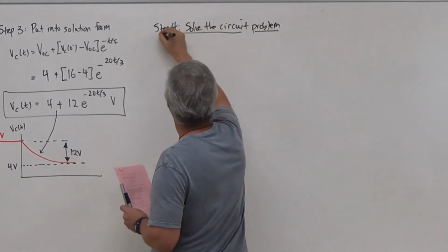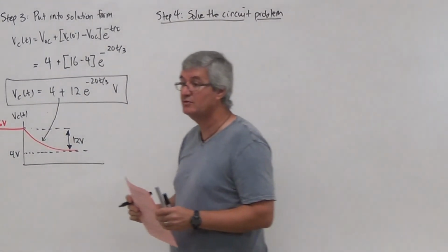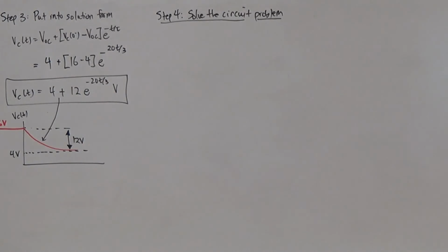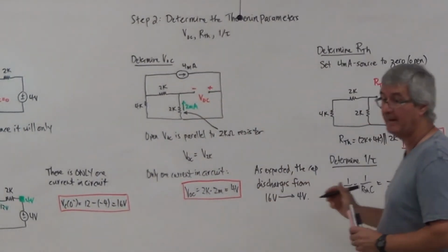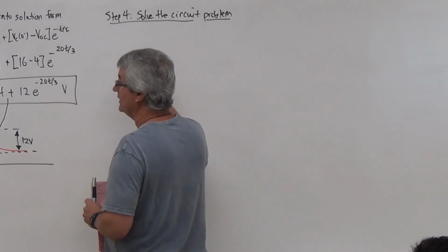So now that I'm armed with this equation for the voltage of the capacitor, I go back to the original circuit. So I would say that this is the original circuit right here, right? We've reduced these resistors right here. We've gotten rid of the voltage source. All I got to do is add the cap back into that circuit. So now I have this guy.